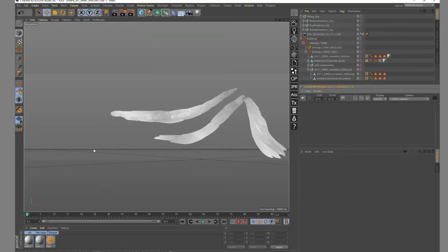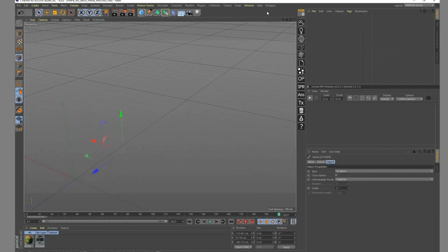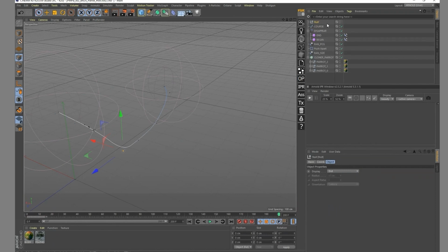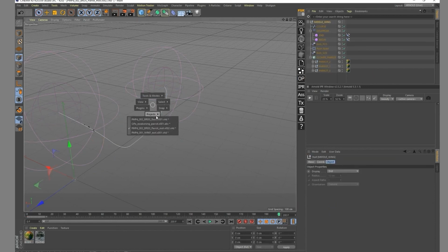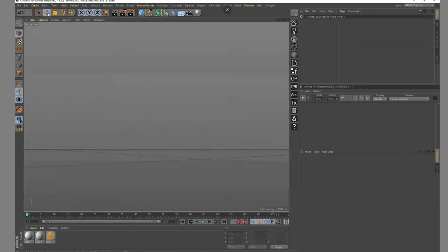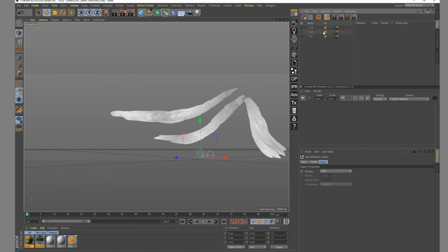So I'm going to work with one wing, which is this one, the middle one. I'm going to go back to what we did before. Put everything inside of a null. I'm going to call that middle wing. Go back here, copy and paste it inside of our project. Also, I'm going to save that file incrementally. So right now, if I'm doing any new render, it's not going to overwrite what we did with the take system right before. It's going to be named version 2.